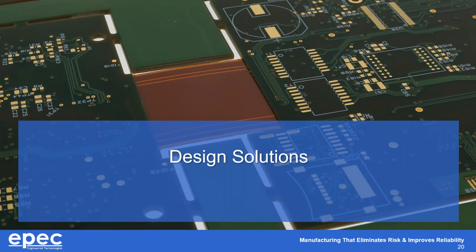So before we get into the design solutions, just to summarize a little bit, we've got our electrical requirements, some of which inherently drive up the thickness of the flex circuit. And then we've got our mechanical requirements that in order to meet a bend requirement, we need to keep the flex circuit as thin as possible. So the electrical requirements and the mechanical requirements tend to be very much mutually exclusive. And when you combine them, they don't always like to play well together.